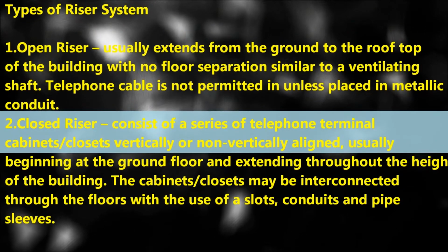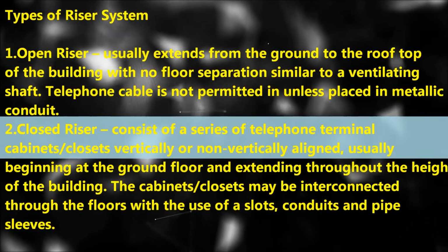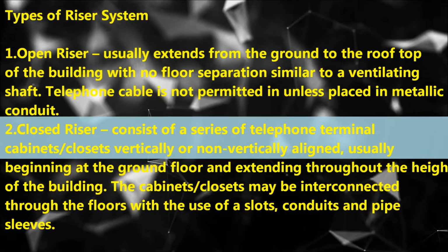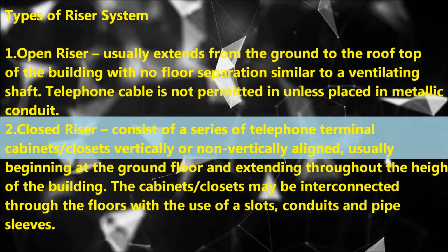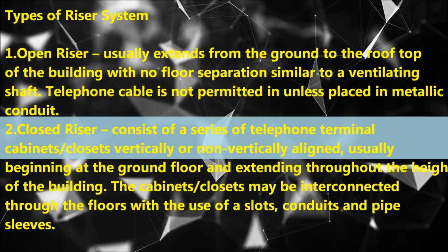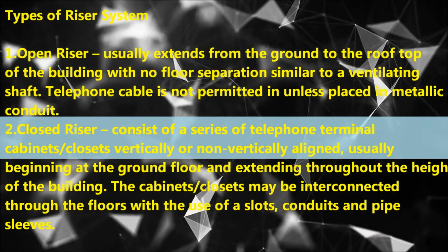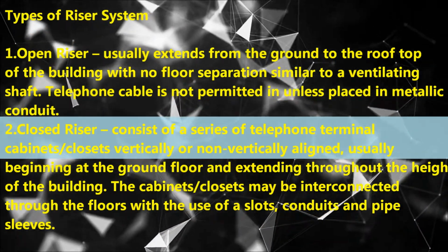Types of riser system. 1. Open riser usually extends from the ground to the rooftop of the building with no floor separations, similar to a ventilating shaft. Telephone cable is not permitted in it unless placed in metallic conduit.